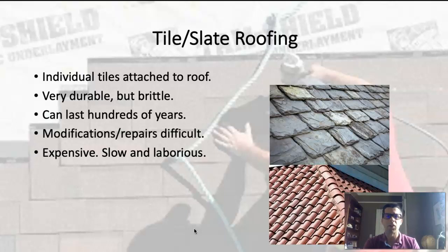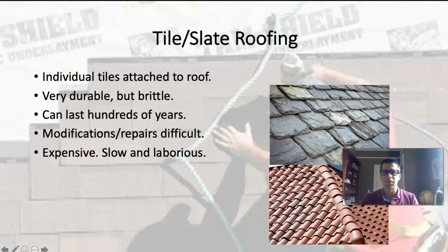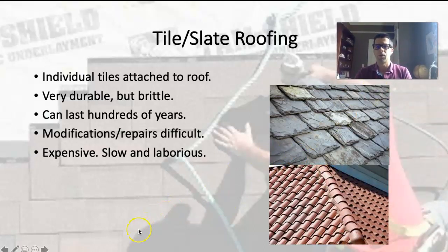Slate tiles, terracotta roofing tiles can last indefinitely. They tend to not get broken down in the sun, which is kind of the doom of most other roofing materials. And there's not going to be a mushroom decaying them or termites eating them or anything like that. So they could theoretically last forever, but the problem is they're so brittle. And so repairs become kind of a really big deal.